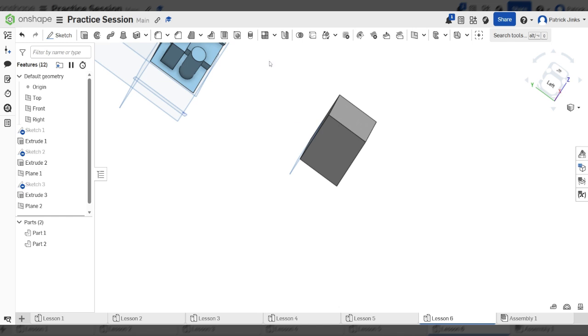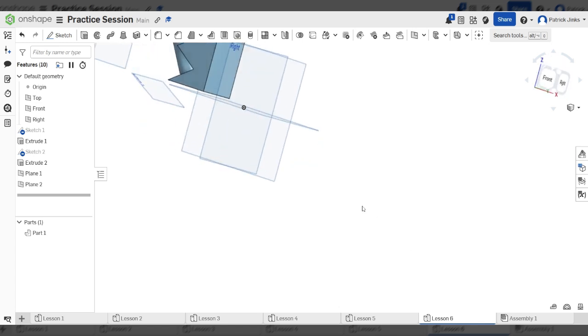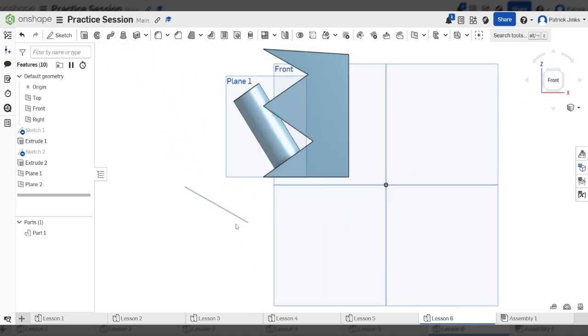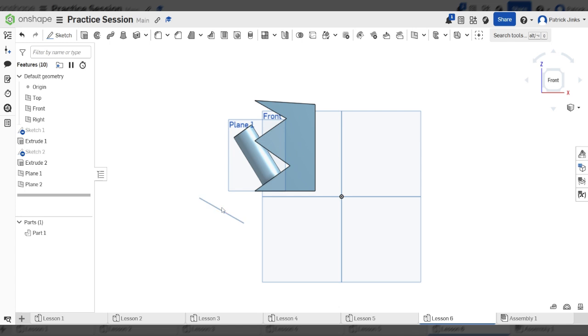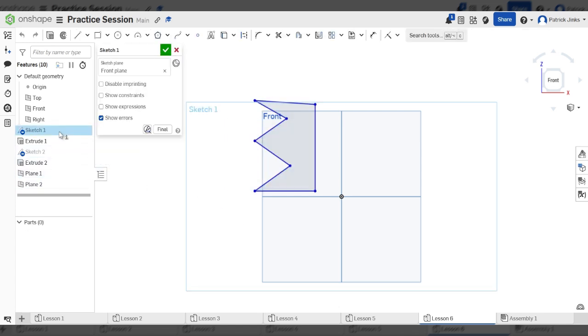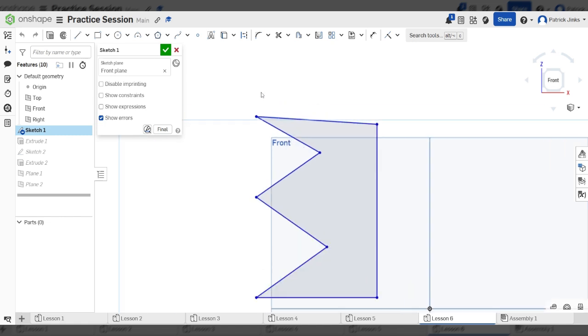I'm actually going to get rid of this now because it's in my way. And the great thing about this is I can now control what angle this is. If I go back to my initial sketch, and I set this angle to 45 degrees, well, first I'm going to set this to 90 degrees. And the way I do that, if you remember all the way back to video 2 or 3, the dimension video, I click dimension or just press D, and that will toggle that grey in or out. I want to make sure it's greyed out.